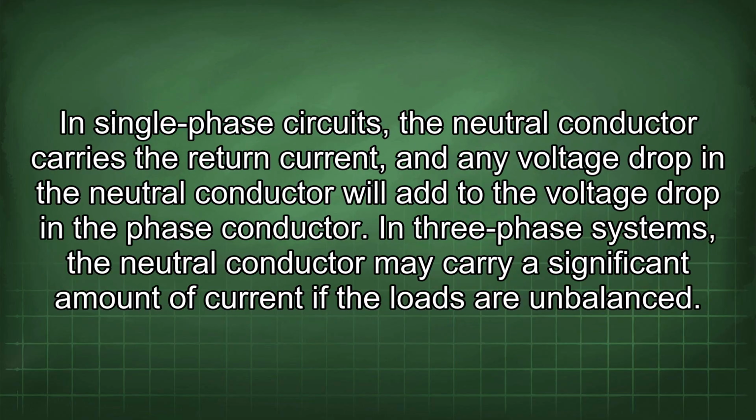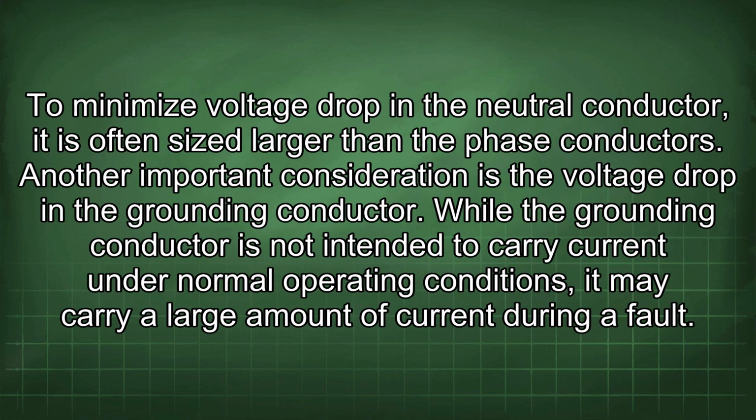conductor. In single-phase circuits, the neutral conductor carries the return current, and any voltage drop in the neutral conductor will add to the voltage drop in the phase conductor. In three-phase systems, the neutral conductor may carry a significant amount of current if the loads are unbalanced. To minimize voltage drop in the neutral conductor, it is often sized larger than the phase conductors.